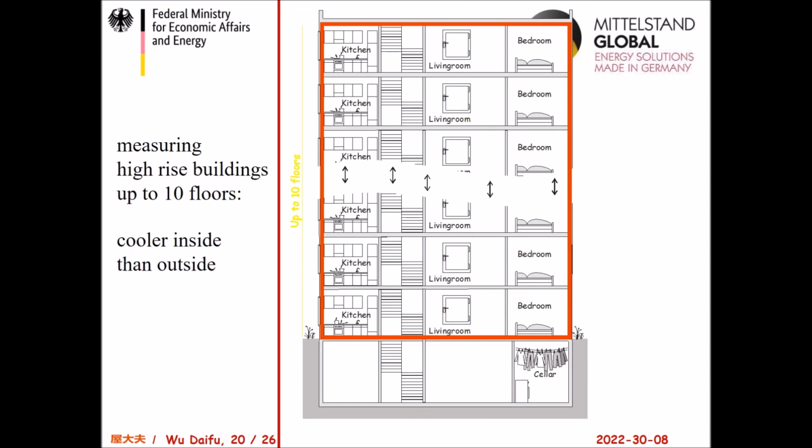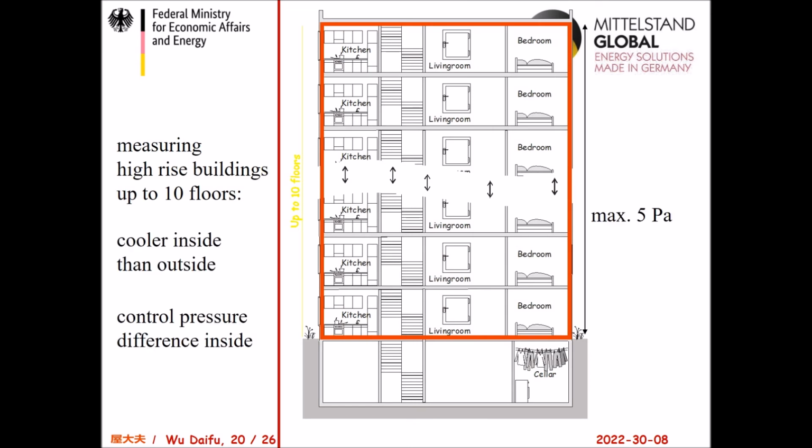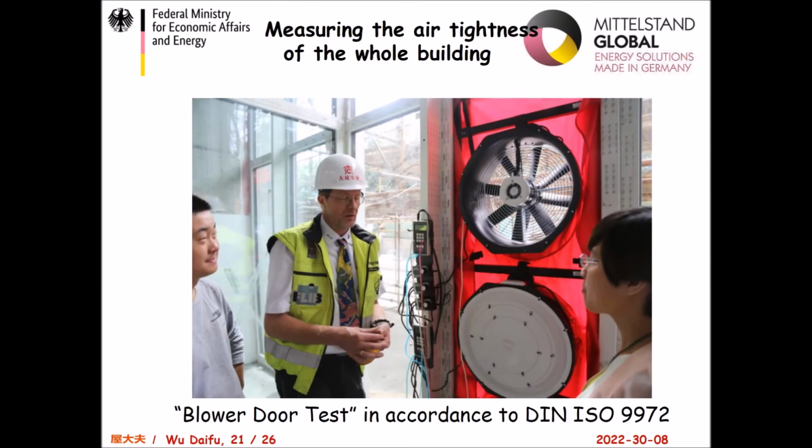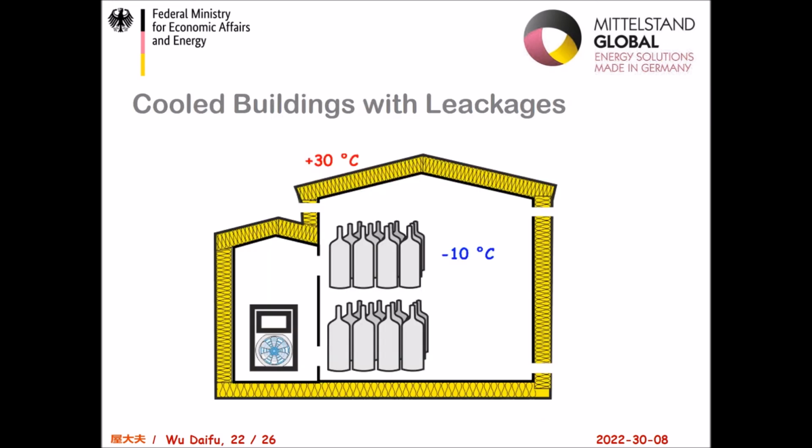And as you can see, it's not only small houses. We also can do airtightness tests in very high-rising buildings. There are some tricks, like it should be cooler inside than outside when we do this, but I can handle you some more ideas when you have the order to do an airtightness test in a bigger building. In those big buildings, you don't need only one blower. So you need more energy, so you can use more than one. 2, 3, 4, doesn't matter. You can just put them into the building and do the pressurizing test. It's not the problem.